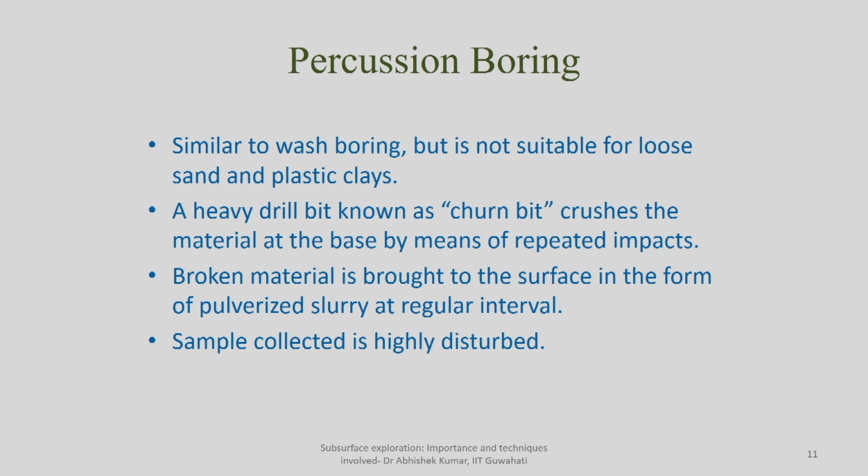So that's how, if you are encountering stiff material, rock medium or gravelly medium, you can proceed to deeper depth. Again, as you can observe here, the soil sample you are collecting is based on impact load, so it is considered a highly disturbed soil sample. So this is about percussion boring.